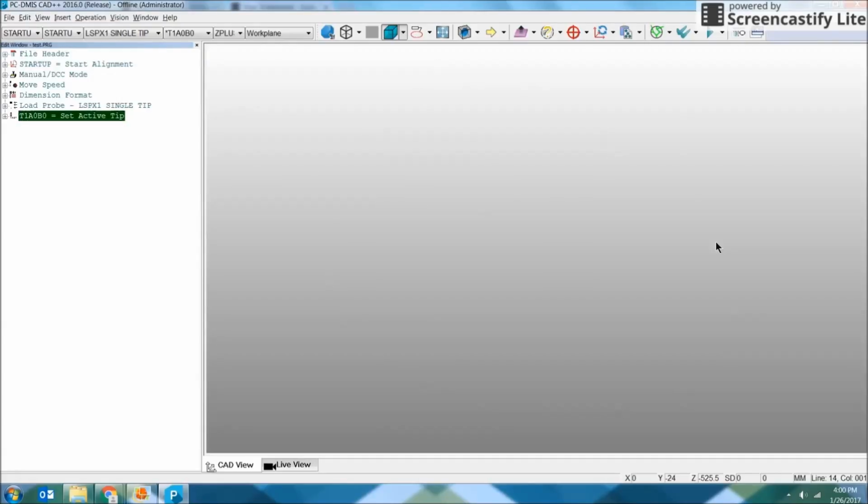Here on the right is our graphic display window. Any 3D CAD data and any features we create will show up over here. And then up at the top, of course, we have our menu tree and two toolbars that put some favorite commands from that menu tree right at our fingertips. The first command we're going to use our toolbar for is to import our customer's IGES model.